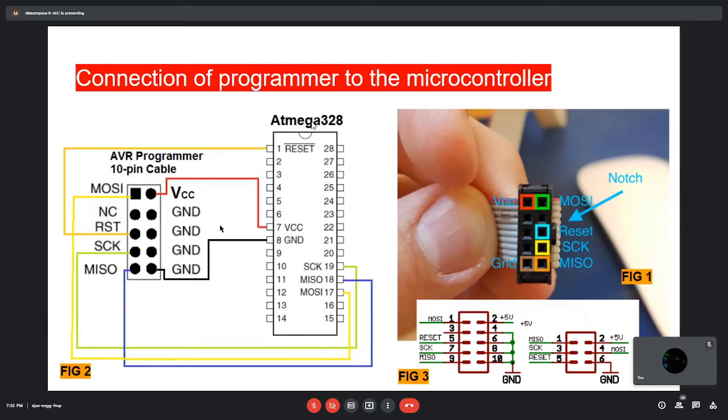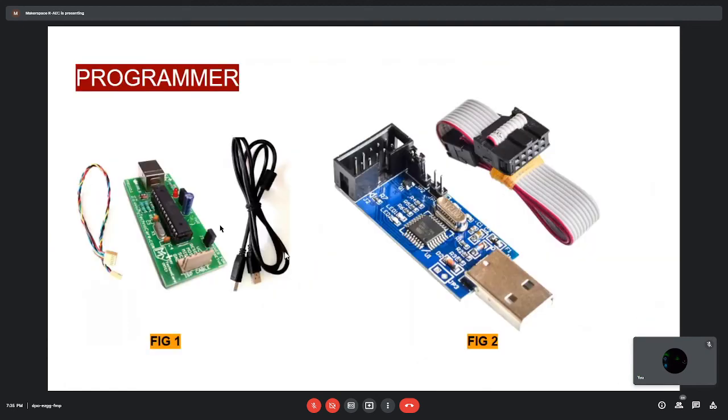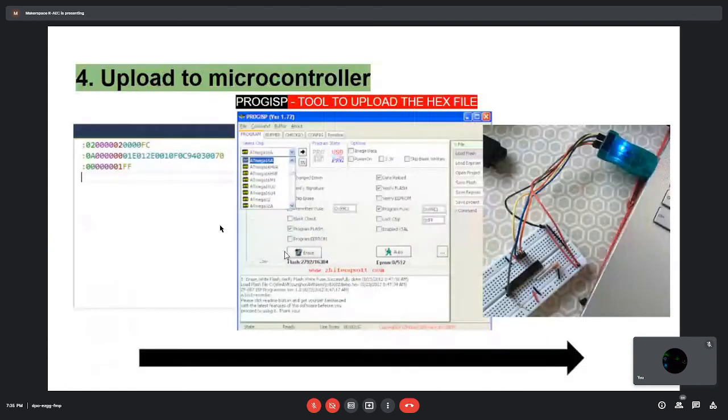Look at this ATmega328. This is the same microcontroller found in Arduino. Here we have SCK, MISO and MOSI. You connect these with wires to the pins here, using a male to female header maybe. The header is connected, and the next part is connected to my programmer. In that way you get this. For example, in a diagram you get this.